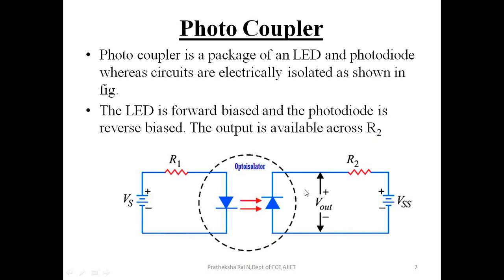A photodiode is present in front of the LED so that light from the LED directly strikes the junction of the photodiode. The photodiode is in reverse biased condition. The reverse bias circuit of the photodiode forms the output circuit of the system. We also ensure that no other light falls on the photodiode junction, and the system is protected from any external light except the light coming from the LED. Initially, no voltage is applied to the LED, hence the LED does not glow. In this condition, as no light falls on the photodiode, there will be only dark current.